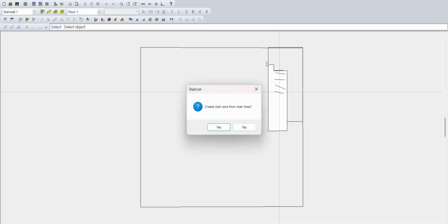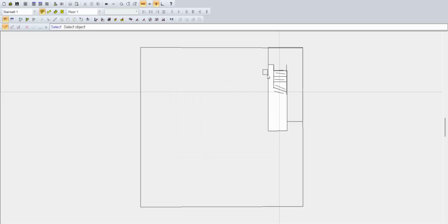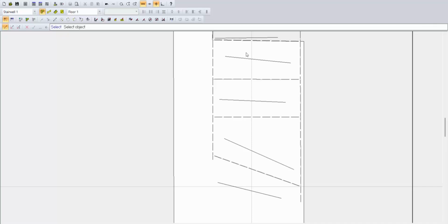You said that it's a floor opening, and like I said, I think when you put the things in the layers, when there's a wall, that would have been walls. And now it's also asking, okay, I detect that you also did some stair cores or one stair core. Do you want it? And I say, yes, I do. And yeah, I want to have the height as well. So you actually see now here like a stair core.